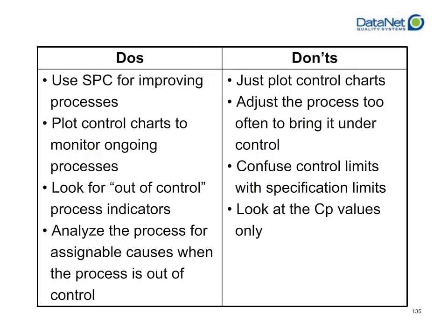You do want to use SPC for improving your process. If you're not going to use it to improve your process, if you're using it maybe just for regulation, then you're not really going to get a whole lot of return on investment on the effort. And if you're just going to be plotting control charts, and you're not going to actually be doing anything with these control charts or with these check sheets for that matter, you're wasting your time.